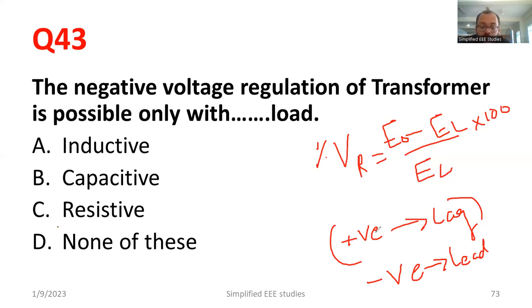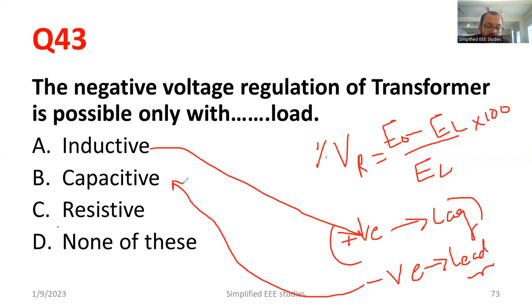Therefore, for this case, you need to select the inductive load. For negative, if the voltage regulation is negative, then the power factor of the load will be leading power factor. That is applicable for capacitive load. So here you can tell me which is the right answer. The right answer will be option A, if the negative voltage regulation implies it is applicable.